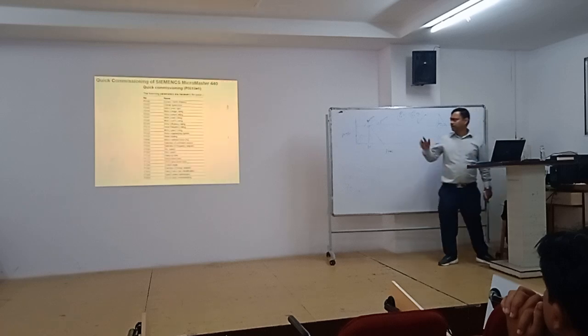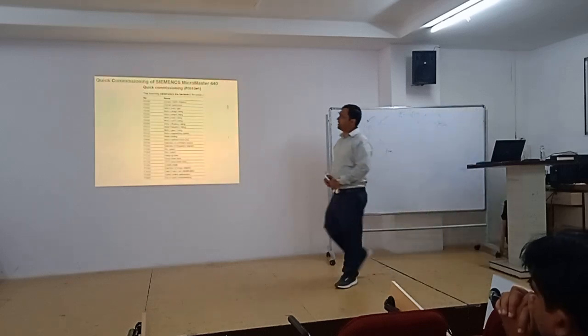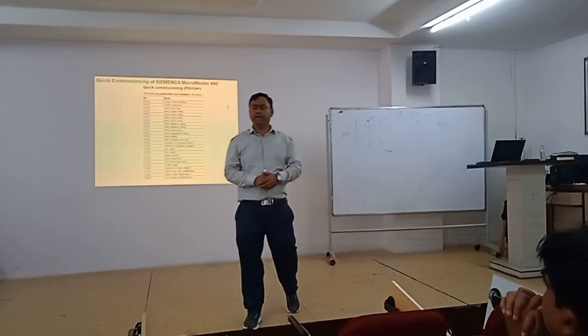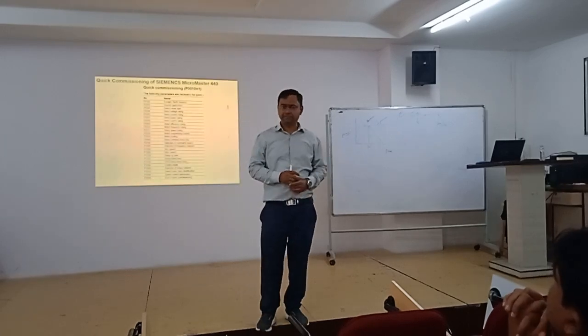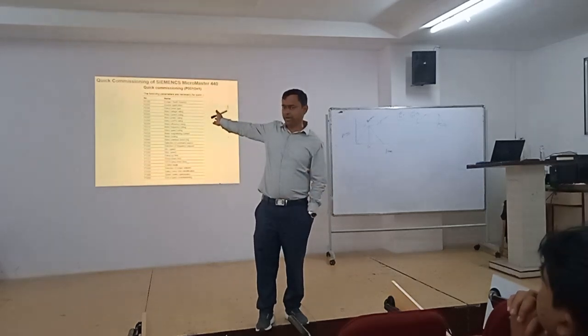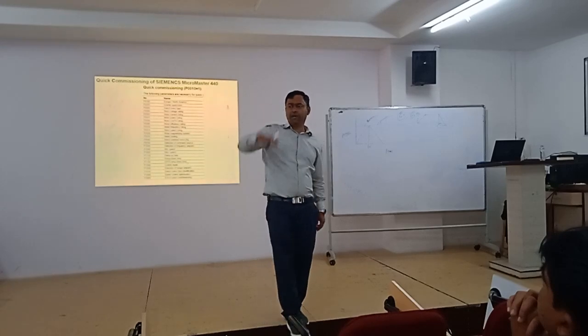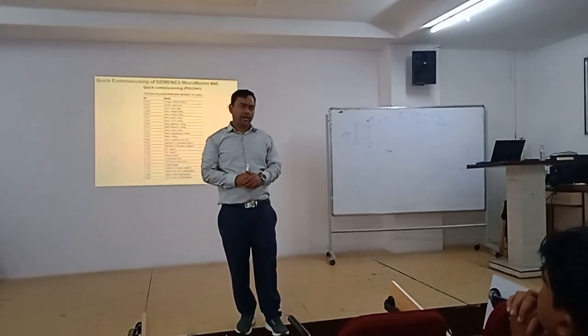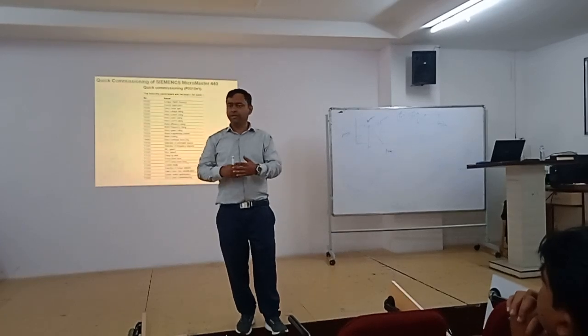So actually, whenever you want to start any VFD, you will configure it. That is actually called parameter setting. This VFD is a Siemens MicroMaster 440. In this VFD, you have to do the quick commissioning, and you can do quick commissioning only by configuring some parameters.